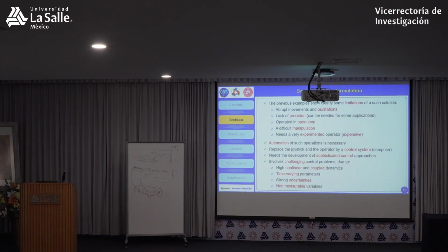However, in this case, as I told you, a PID controller is not enough. You need to develop a better controller, and you will be facing several challenges. The challenge is that the system itself, as I explained in the first lecture, is a complex robotic system. Because of the highly nonlinear dynamics, there is a coupling between the degrees of freedom. There are time-varying parameters, strong uncertainties. You cannot measure everything, like position X and Y of the underwater vehicle, impossible to get it. You have no sensor to measure it. And so on. All those challenges, you have to deal with them when you design a controller.